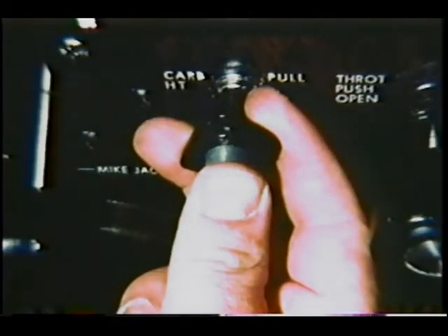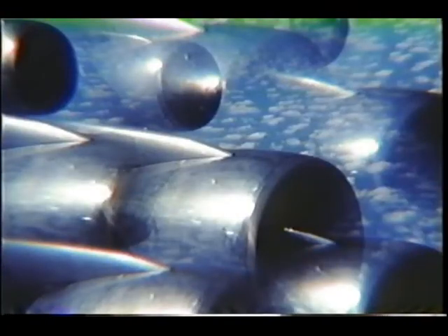And always push the carburetor heat or alternate air to the full off position. In a go-around, either carb heat to off or full power may come first. But if full throttle is added first, it must be a smooth application to assure engine response. If you've got a turbocharged airplane, watch that manifold pressure red line. And if you're flying a turbine, monitor those engine power gauges.